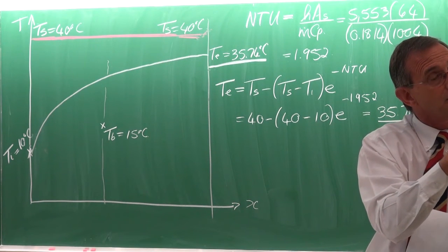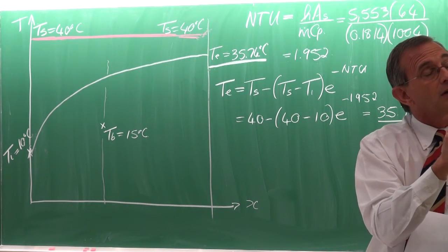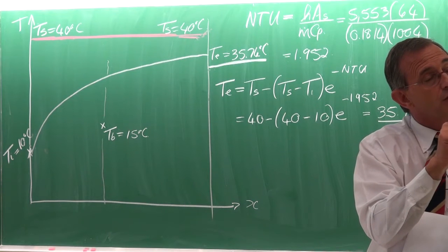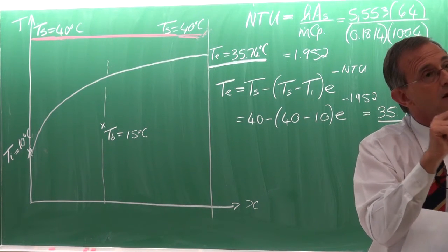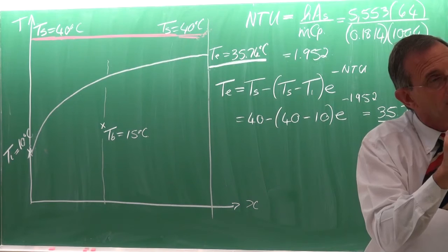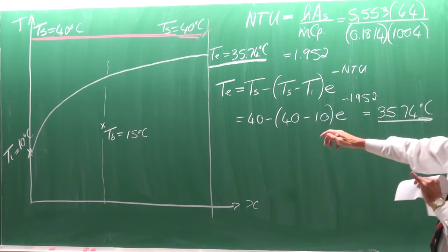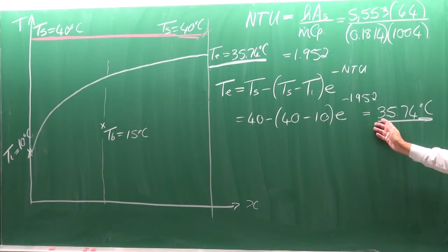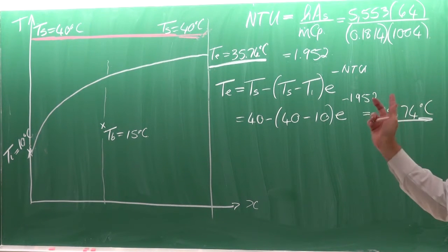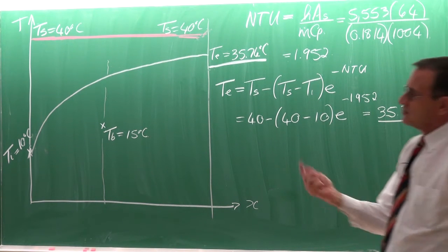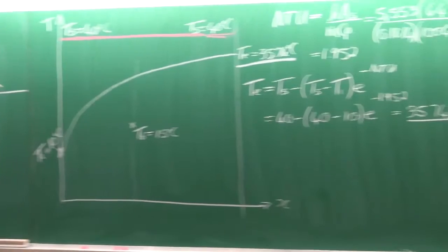But also the Nusselt numbers are based on the Reynolds number, and the Reynolds number is also based on the hydraulic diameter. But if you think of this derivation that we did here, we worked with the area of the control volume. And I think that's the reason. So I think this is correct to use this area and not that of the tube. So let me just go back and revisit this.